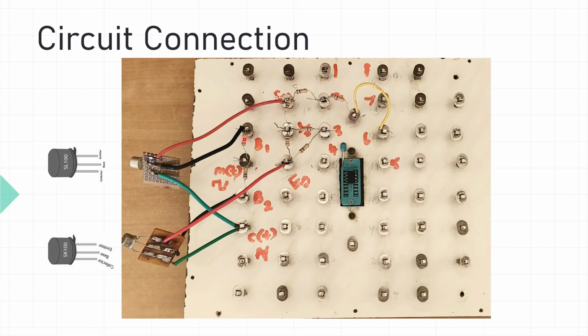I have connected a 10K resistor here and connected the bases of the transistors to the two ends of the resistor, and here I am going to apply the message signal, that is square. Now I connect the emitters of the two transistors to this 1K resistor, and this terminal will be the common ground.